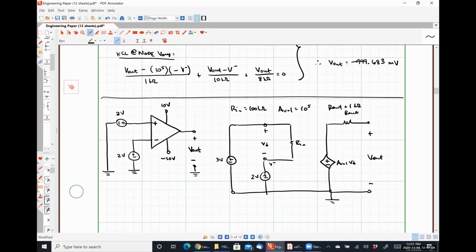So we have an amplifier circuit, and it can amplify very, very small signals, but as soon as we get beyond a certain point, it saturates and pins the output to either VCC plus, which is this 10 volt here, or VCC minus, which is this negative 10 volt supply there, because our output can never exceed our power supply voltages in an op-amp. And that's assuming that we have what's called a rail-to-rail op-amp.